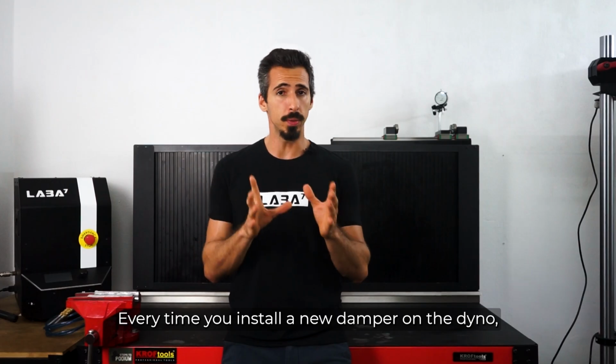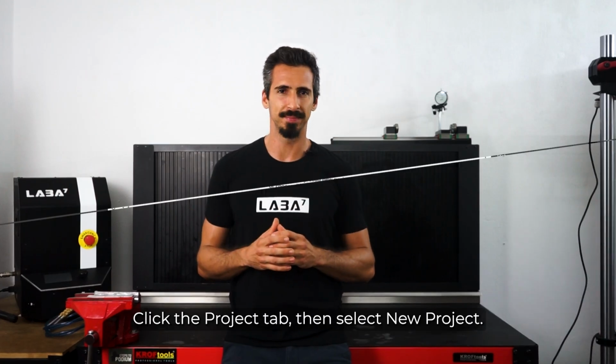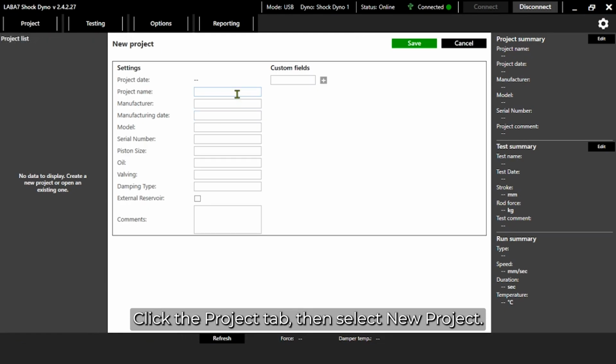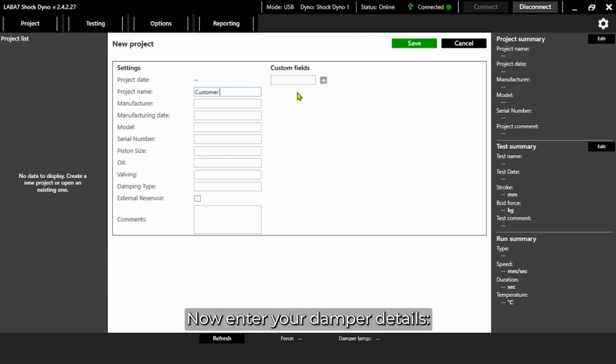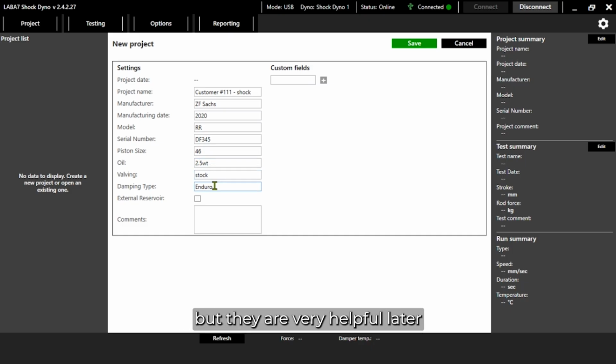Every time you install a new damper on a dyno, it's best to start with a clean slate by creating a new project. Click the Project tab, then select New Project. Now enter your damper details: manufacturer, model size, piston size, damping type, oil type, valving setup, and whether it has an external reservoir. You can also include optional notes such as vehicle details, rider or driver feedback, or baseline settings for a previous build.